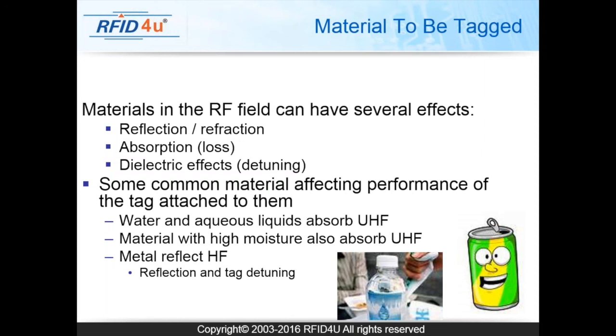Some common materials affecting performance of the tag attached to them: obviously water and aqueous liquids absorb UHF. If you take a standard UHF tag and read it in open air, it will read fine. If you attach it to a water bottle full of water, then you won't be able to read it, or possibly get a very short read range, an inch or two, but you won't get the same read range that you get in open air because the water detunes the tag.